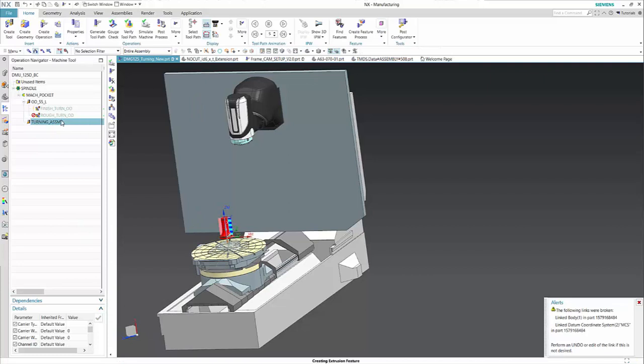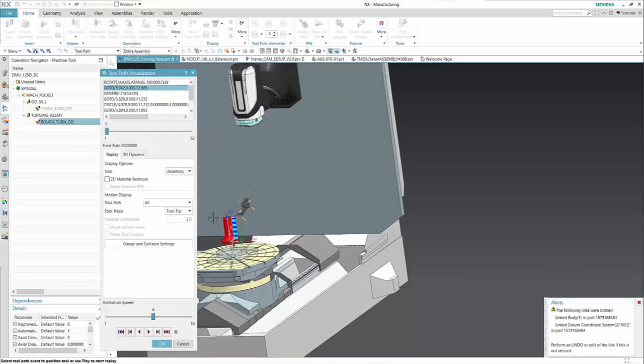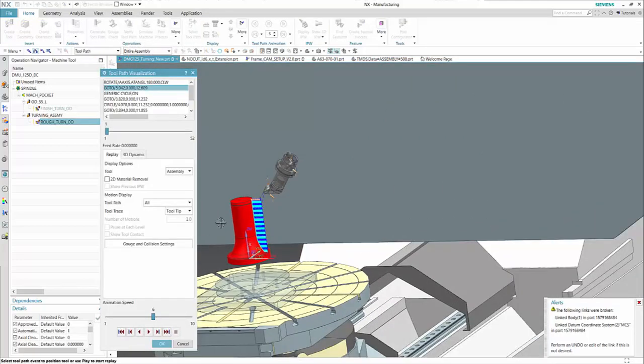Okay, and we can drag down an operation, generate the new tool path. Once we have that, we can jump in and do verification. This is something we didn't do with the milling assembly, but you can see here how easy it is to use the turning assembly that we just created here in verification after generating that new code. This is very useful if you do not have a machine kit to simulate. You can see here that our tool assemblies work in verification as well.